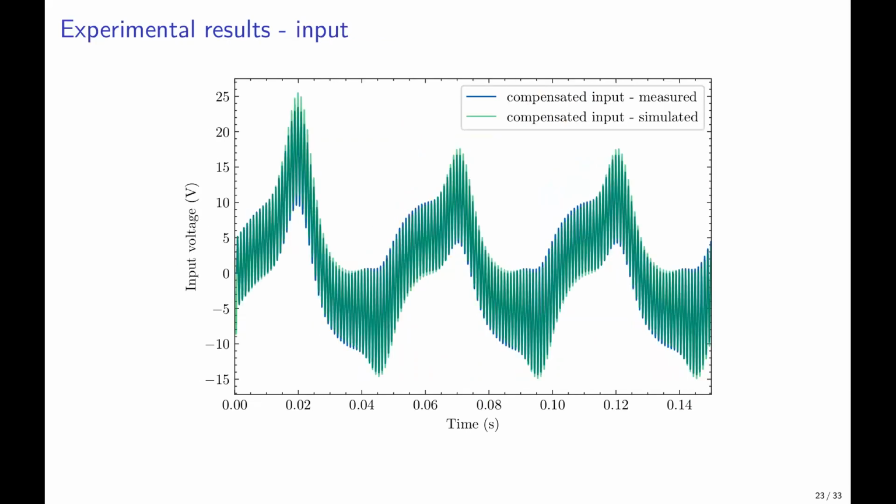Now when you do this experimentally, here I'm showing the desired output signal, and then the output signal that you actually measure, and those are not always exactly the same. What I'm doing right now is modeling the amplifier, or the whole output chain, audio interface and amplifier, as something that has just a gain and a delay.